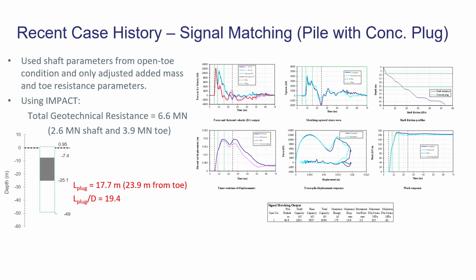And if we take that, the shaft model parameters, and we're not getting into the details of all that, we go and run it through, we vary the plug parameters nominally, and basically it was, took the concrete plug, broke it into a number of sections, and then started playing with the properties of those sections until we were able to match the upwave curve before the toe, basically before 2L/C.